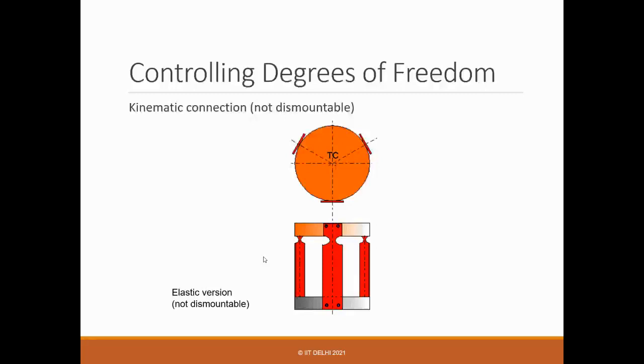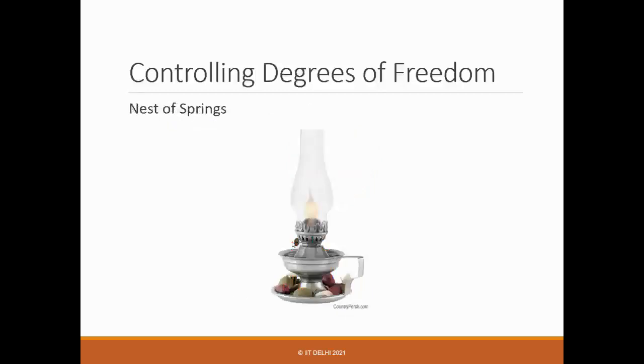Again, you can design non-dismountable kinematic mounts. Kinematic mount is basically you are providing all the constraints. So again, here, suppose very simple, simply take a sheet metal and then laser weld. So laser welding, spot welding you can do, and two spot welds, and then likewise you can get 2 constraints by each, and then you can get 6 total. Very simple.